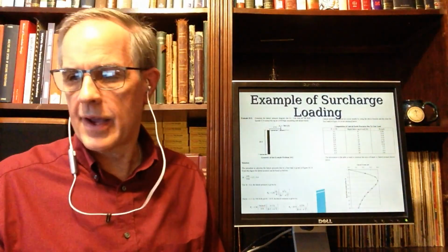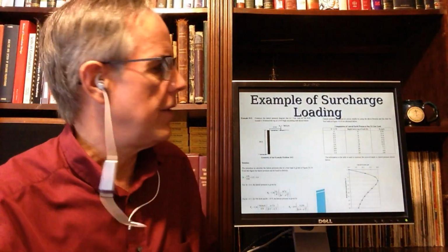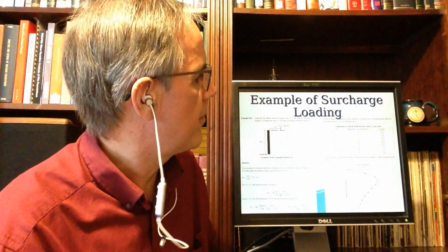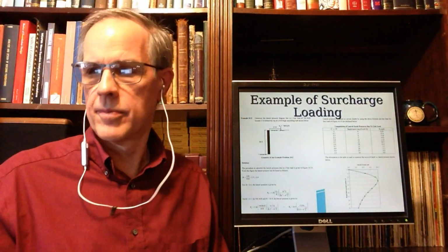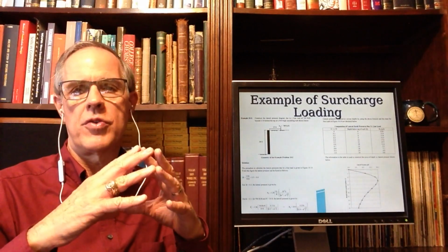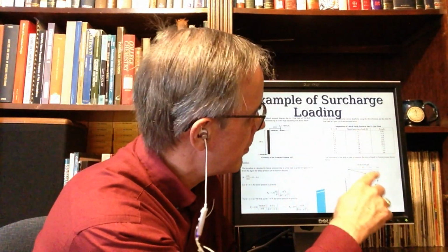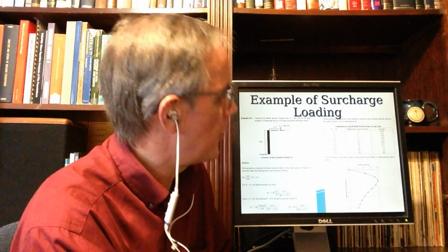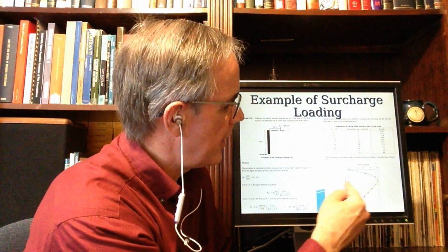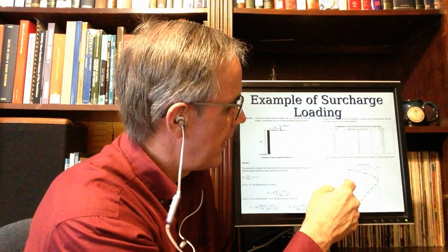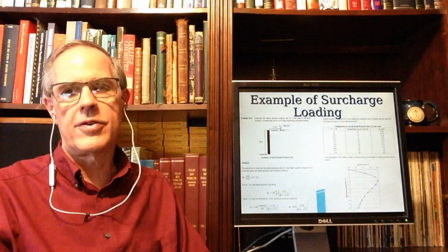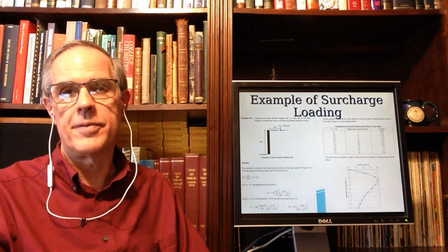Traditionally, in hand calculations, what we've done is we've computed a resultant, where basically we reduce this entire force profile down to a single force, somewhere in here at the centroid of this, and we use that. With hand calculations, that's traditionally the way it's been done.